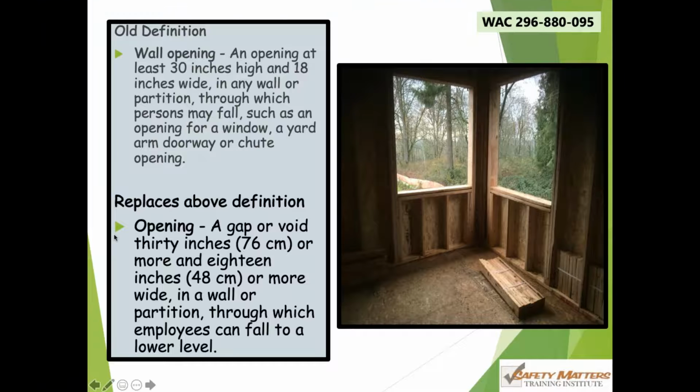Now an opening, this replaces the above definition, is simply a gap or a void, 30, T-H-I-R-T-Y. Sorry guys, this makes me chuckle. 30 inches or more high, 18 inches or more wide in a wall or partition through which an employee can fall to a lower level. So these little windows here, if this window sill doesn't meet the right height, if this is wider than 18 inches, bigger than 30 inches, this needs to be protected. At what heights? We're going to find out.